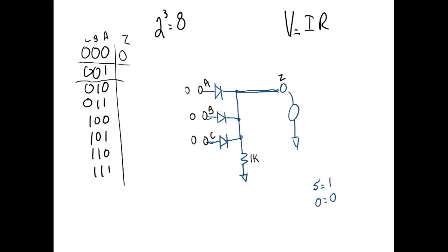People don't understand that, and that's why when you're troubleshooting, if you've got an open resistor, all the voltage drop is across the resistor. Why? Because nothing else is dropping any voltage. Why are they not dropping any voltage? Because there's no I. You've got no current. So everything else is acting like a straight piece of wire, right? Okay, so that's good. So let's see, what would we get out now?